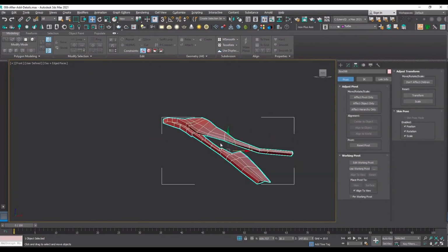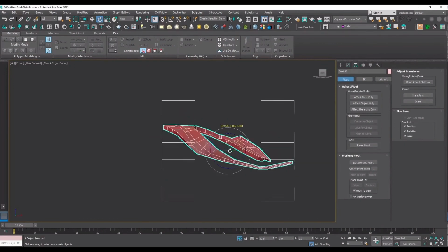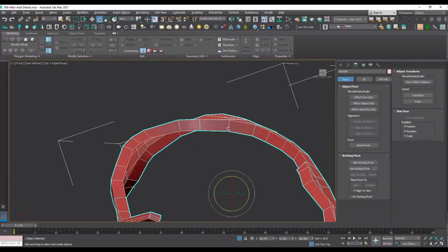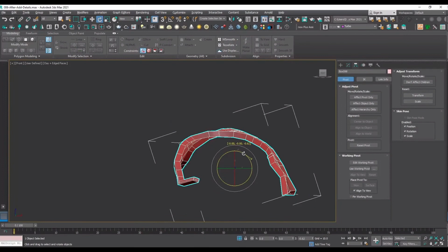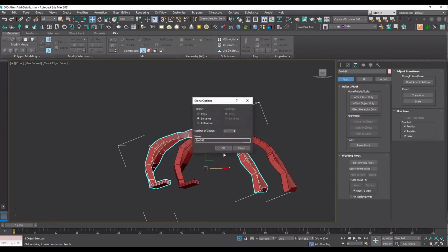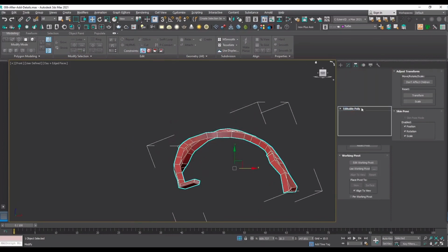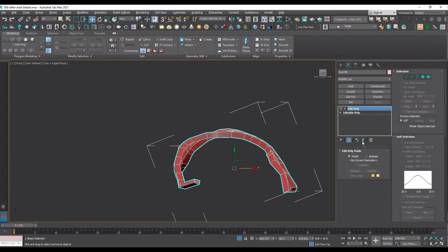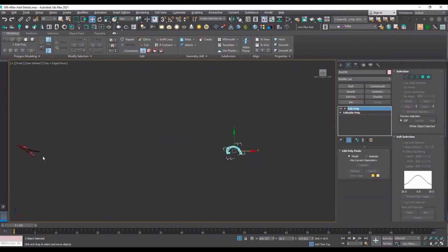I want to rotate it to get a flat and straight surface on top of our mesh, because we want to make it easier to place and extrude on top of the mesh. Otherwise it will be a little bit more tricky, a little bit more challenging.